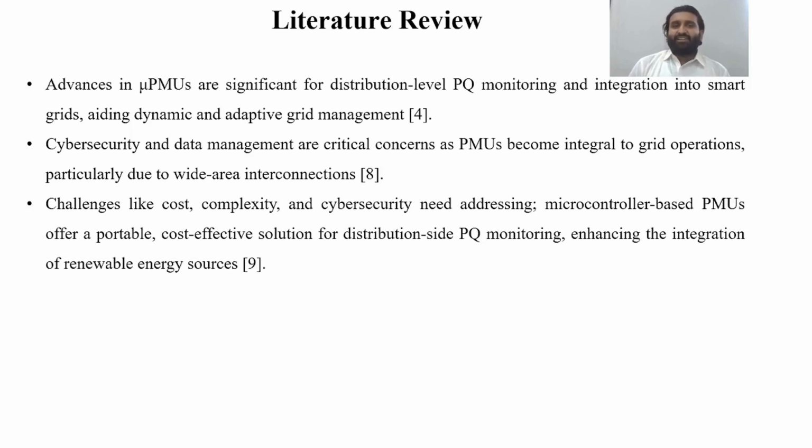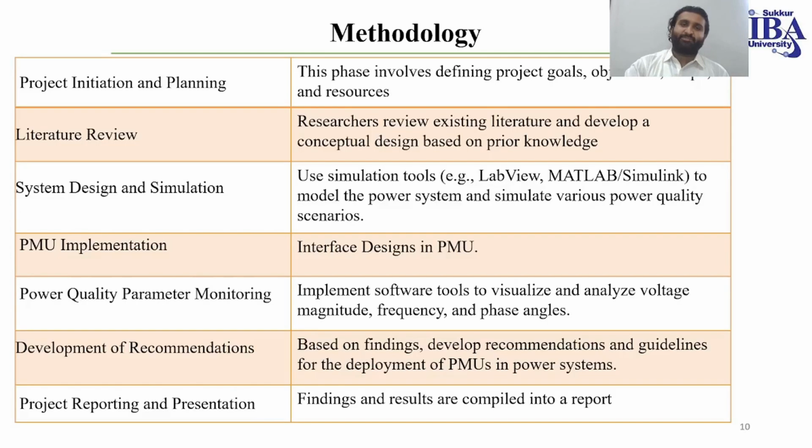Definitely there are cybersecurity and data management concerns that are critical as PMUs become integral to grid operations, particularly due to wide area interconnections. When there is an internet connection with our power systems, there will be cybersecurity issues. So challenges like cost, complexity, and cybersecurity need addressing. Microcontroller based PMUs offer a portable, cost effective solution for distribution side power quality monitoring, enhancing the integration of renewable energy sources.